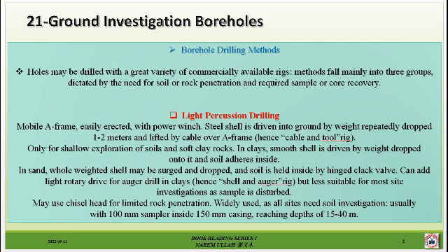In clays, a smooth shell is driven by a weight dropped onto it and soil adheres inside. In sand, the whole weighted shell may be raised and dropped, and soil is held inside by a hinged clack valve. Can add light rotary drive for an auger drill in clays, hence shell and auger rig, but less suitable for most site investigations as the sample is disturbed.